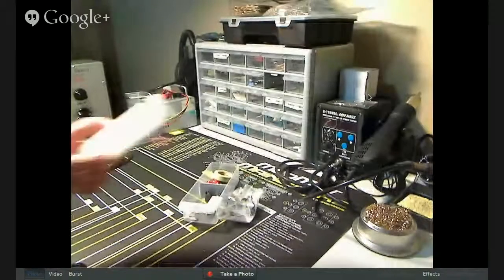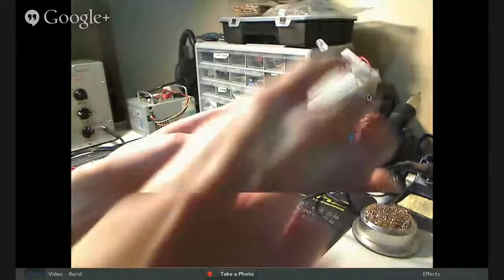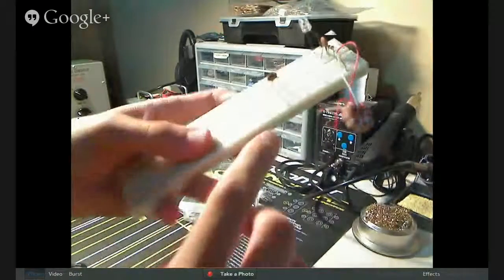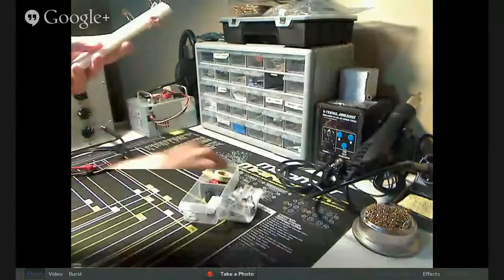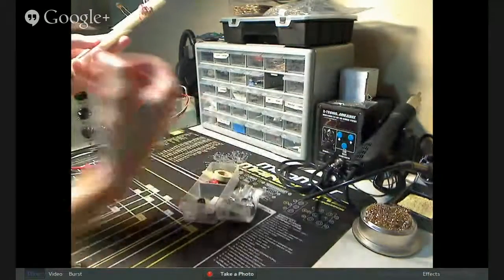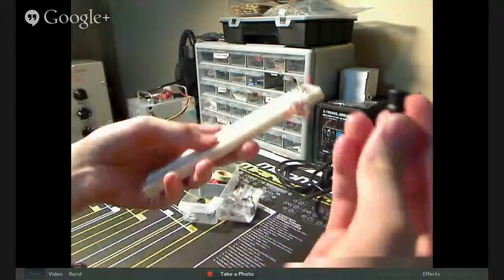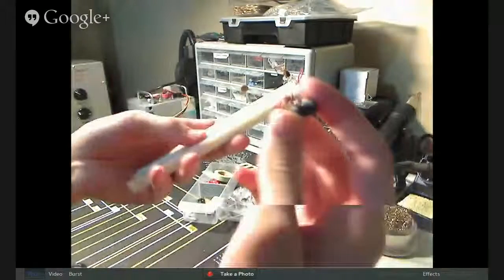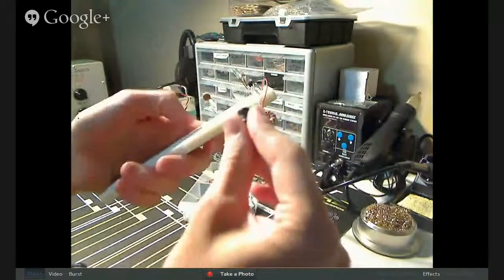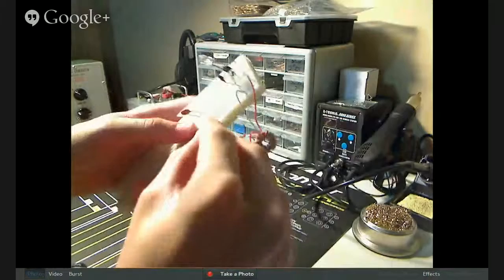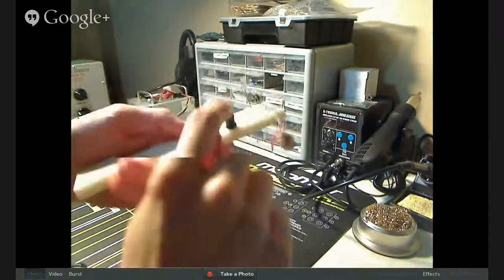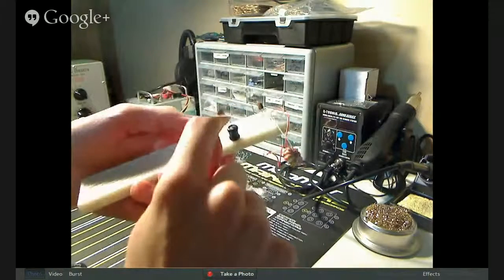I'm going to set up a tank circuit on this breadboard. I'm leaving the Joule Thief we made last time. A tank circuit is just a capacitor and an inductor. I'll use this one. I'm not sure what the value is, and given our equation there, we can use a tank circuit to figure out the value of one of these if the other one is known.